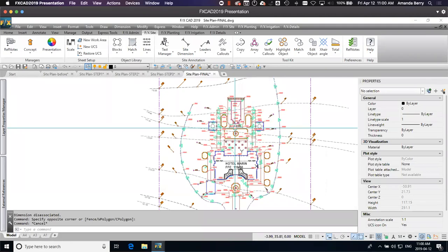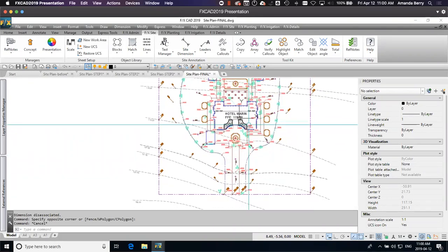But basically you want to keep most of the elements as close to the existing grade as possible. So I would choose the finished floor elevation by what kept everything else as close as possible to the existing grade. And sometimes that can take grading the whole plan and regrading it one, two, or three times.